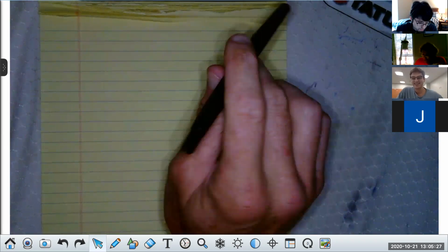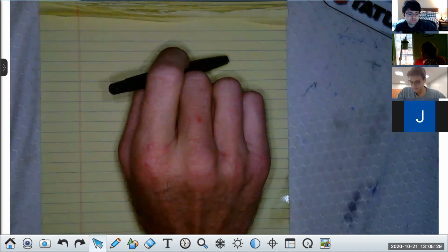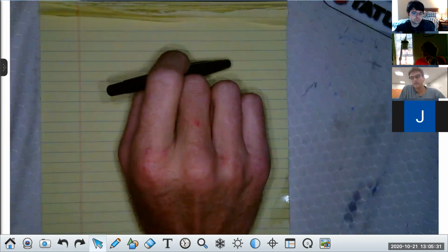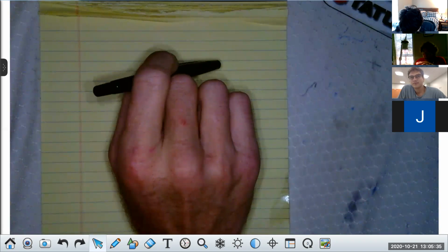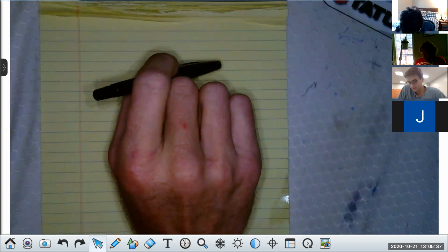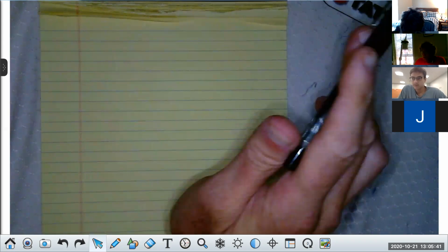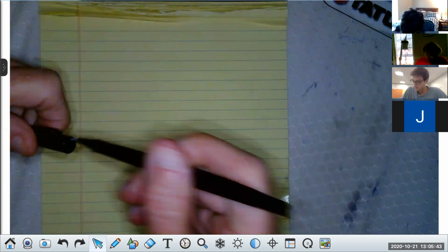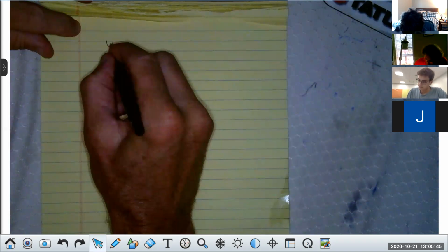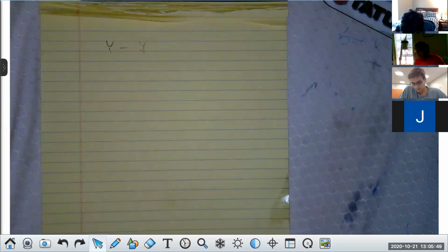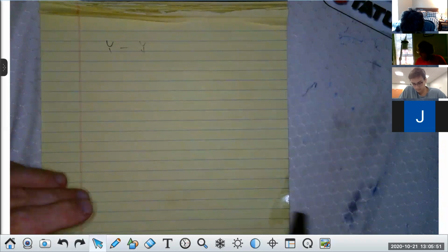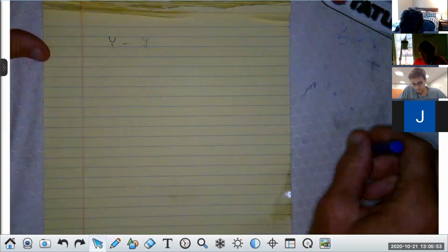With delta Y configuration of systems, I'm going to go through this for a very important reason. People mess up delta and Y often by the transforms. I always tell you this, and I'll say it again, we always do everything in the Y configuration, and then we get whatever information they want. You will not go wrong doing it that way. Does everybody hear me?